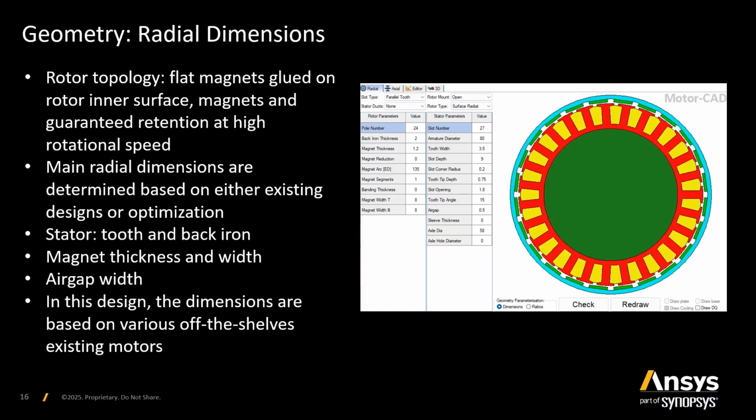So how can we achieve this geometry? This can be done in MotorCAD using the adaptive template approach. Based on a Python script, it's possible to generate customized geometries in MotorCAD, with the advantage of being parameterized and specific to a certain application. Using this technique, we have generated the type of rotor that is now available on the screen.